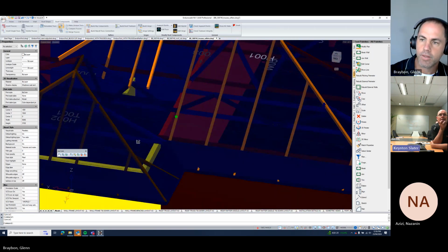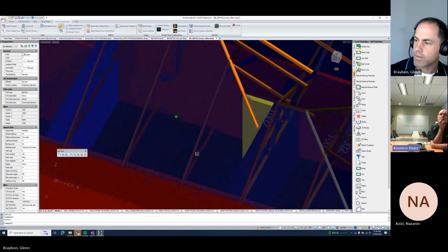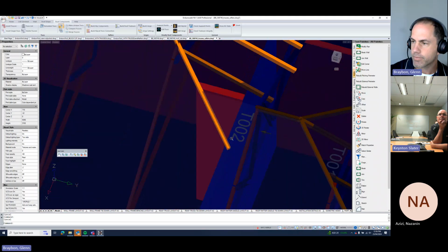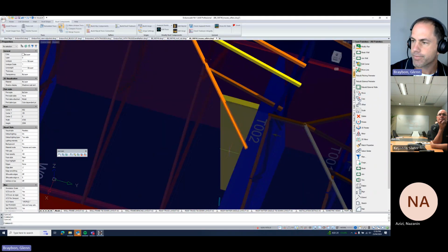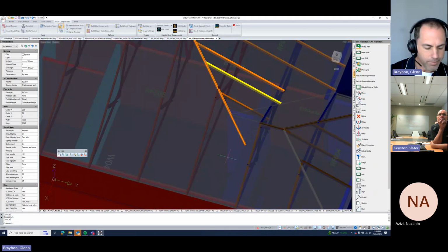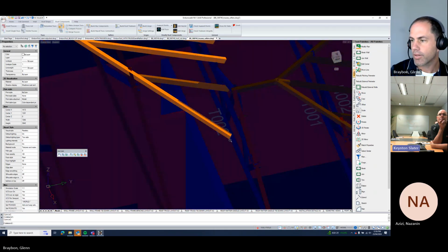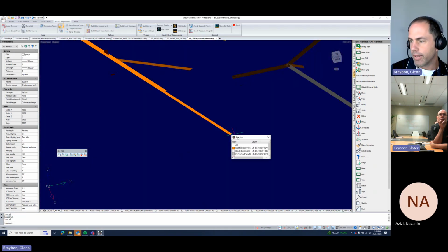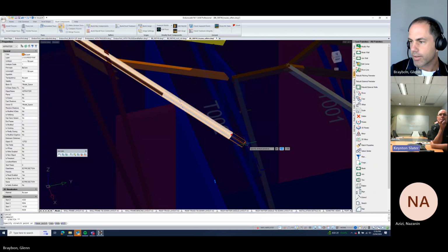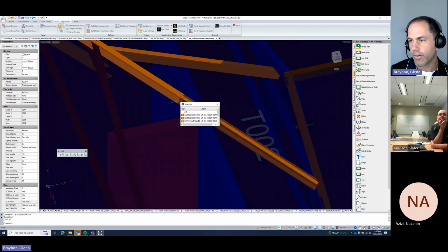So with that hip where you're extending it to that truss cord, I asked you this the other day. Is there any plan to have something there where we could create a bent tab connection for that rafter joining to the back of the truss, where it notches the flanges and possibly even boxes the top cord of the truss? Yeah, agree.